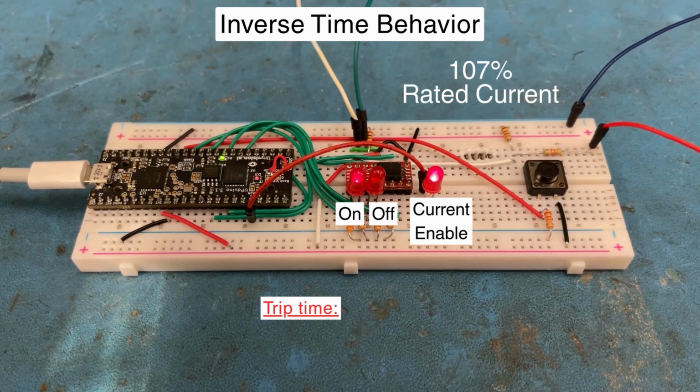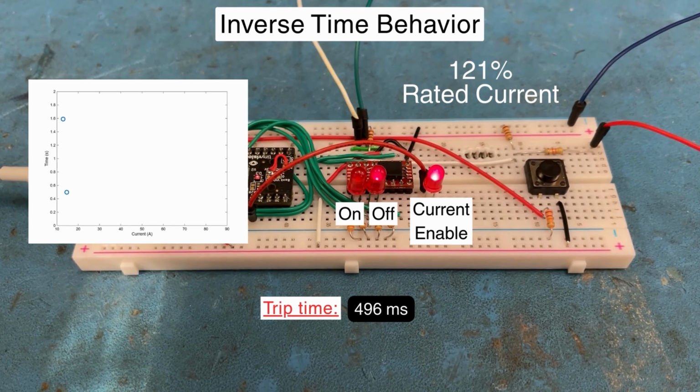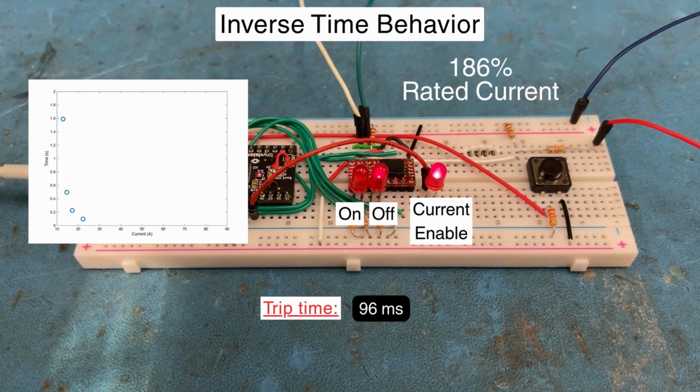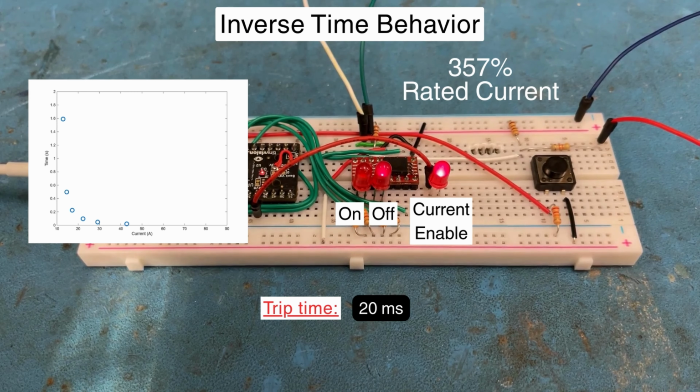To have a more in-depth view of the inverse time curve behavior and how our breaker works, here we have a video showing the time to trip at different rated currents. As you can see, the LED is turned on, and once the current exceeds a certain threshold in the inverse time curve, the LED turns off. This is because the inverse time curve is coded into our FPGA. Also, the speed at which the breaker trips depends on how severe the current is, as a higher current will make the breaker trip faster.